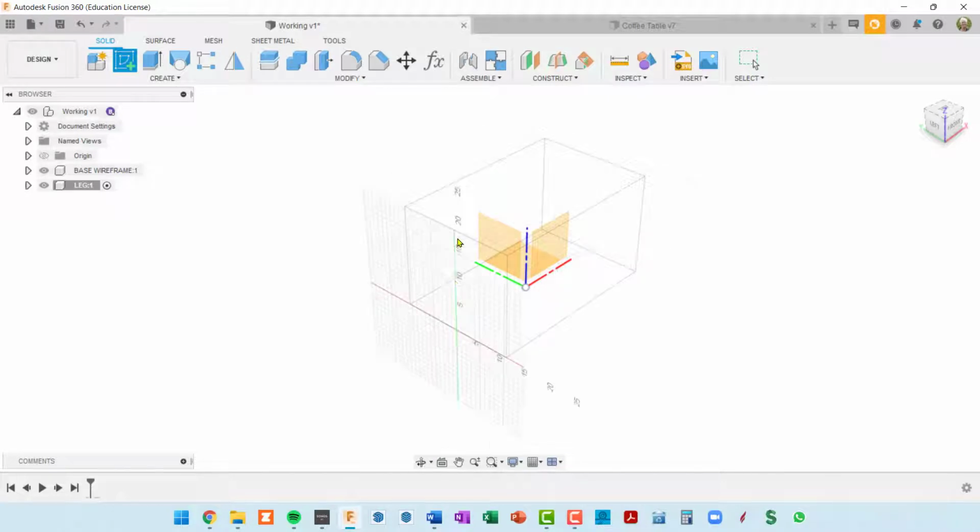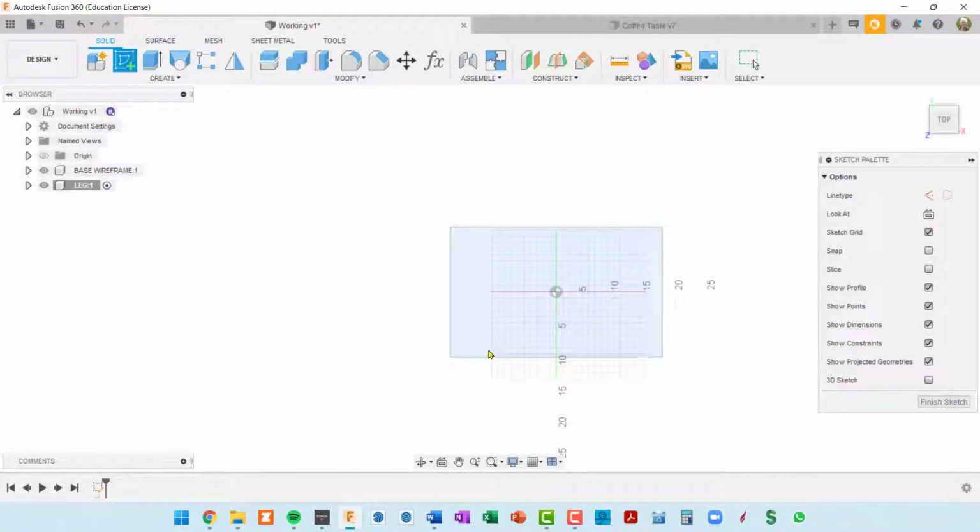But since the wireframe is essentially a solid, it's not letting me select it. So I'm going to hold my left mouse button down to use this drill through technique. And then as I toggle through these various faces, you can see that the grid appears on the 2 faces that I'm being presented with here. So I'm going to pick this second one, which is the face that I want.